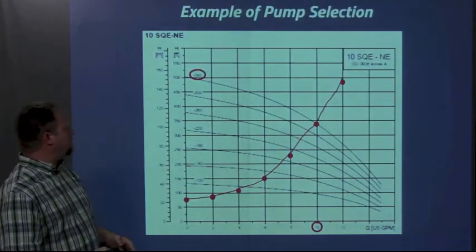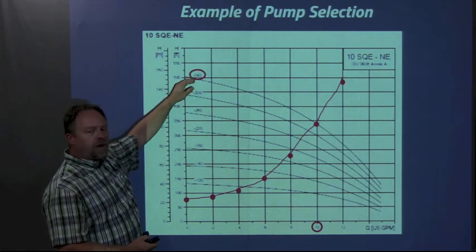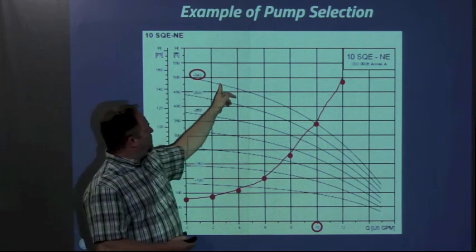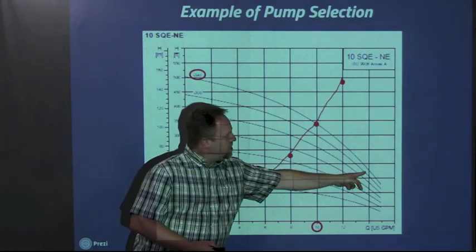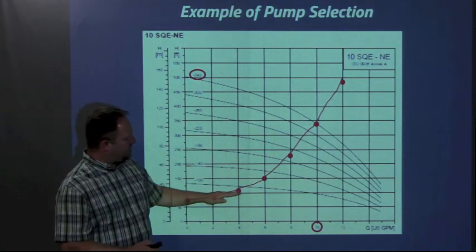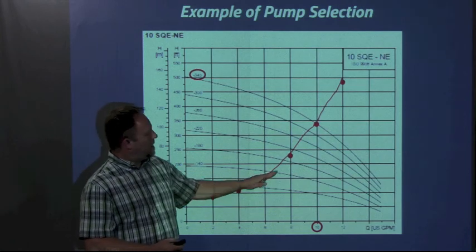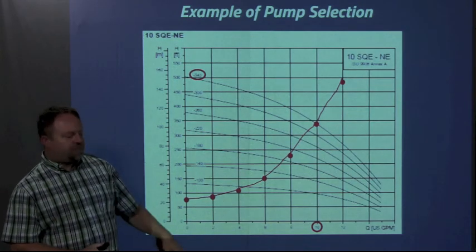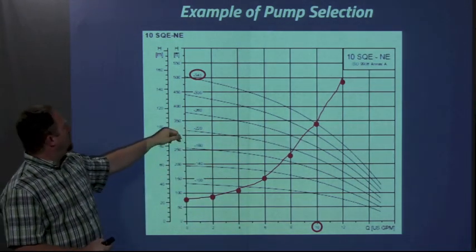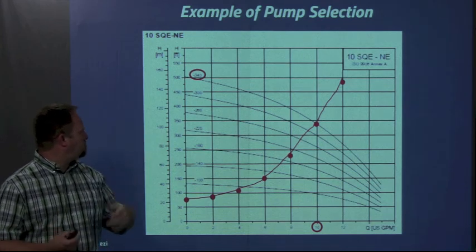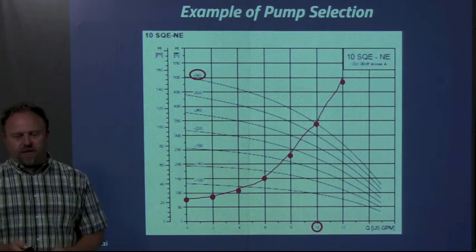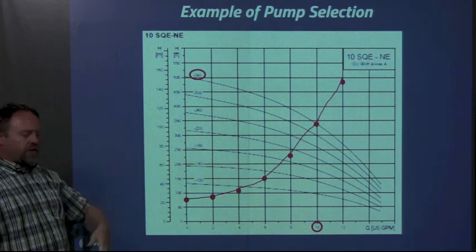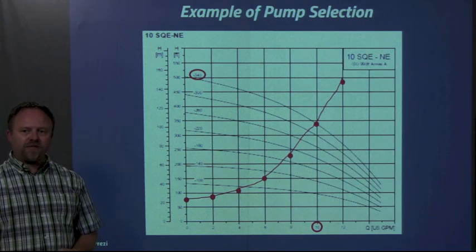In our case here, these are some of the manufacturers for the pumps that we're using. You see these different curves here. I'm looking for this pump. The specific pump here is this curve, and this is my system curve. I plot my system curve at different flow rates. I can see that it intersects right around here, so I can get about 10 gallons per minute with a head of around 320 feet or so. And that's an example of how we might use a system curve and the pump curve in order to select the pump to make sure it's going to be sufficient.